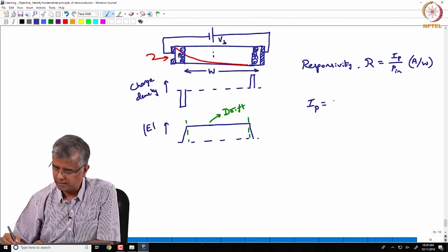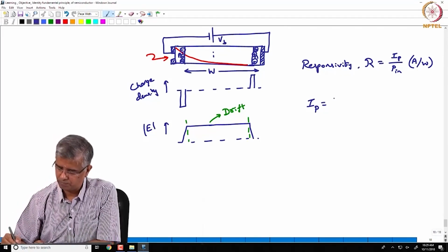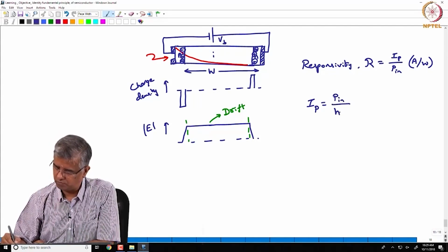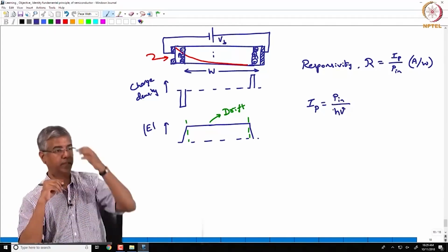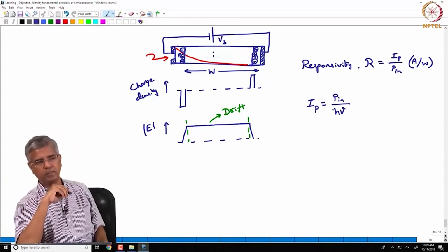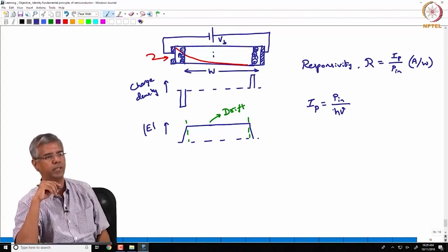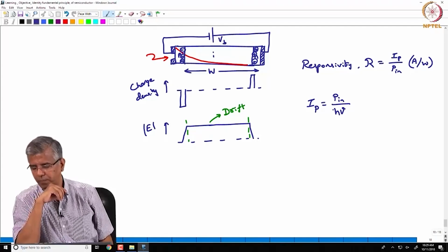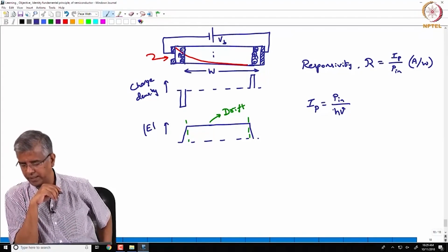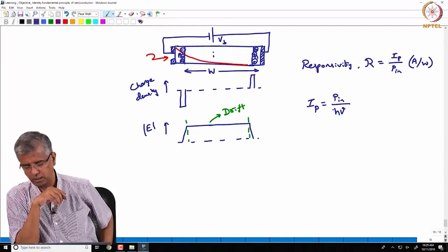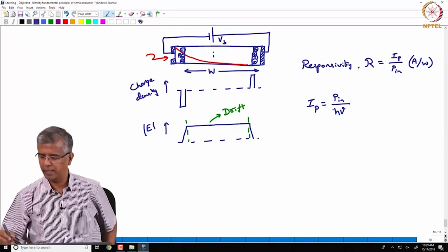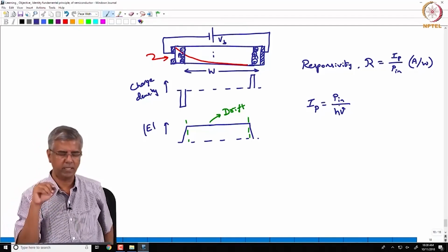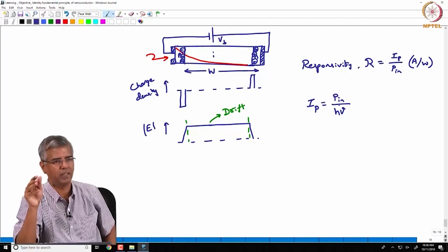So, what exactly is happening when light falls on this photodiode? Now, light falls on this photodiode at a certain rate, okay. That rate, that flux, is given by power over photon energy, right. So, P in over h nu is the rate at which the photons are incident on this, and when they are incident on that material, that material is a high index material, right.